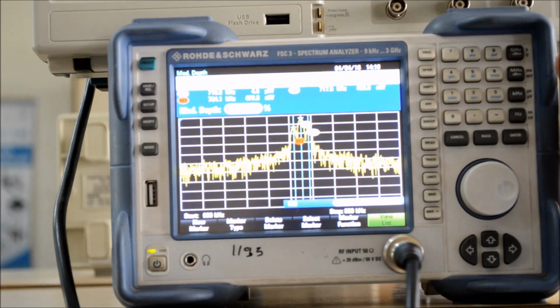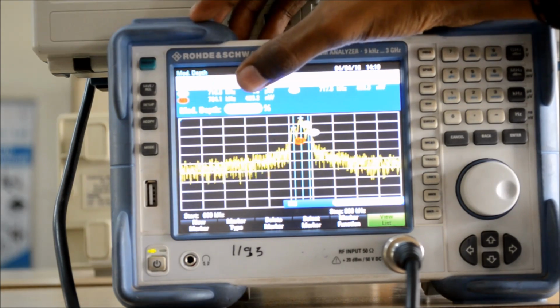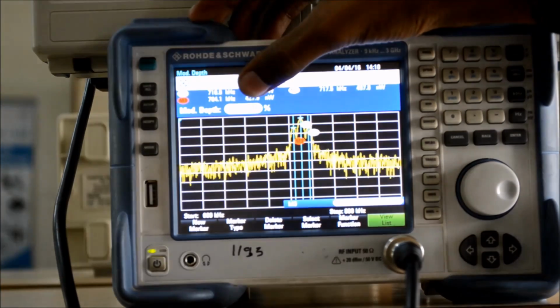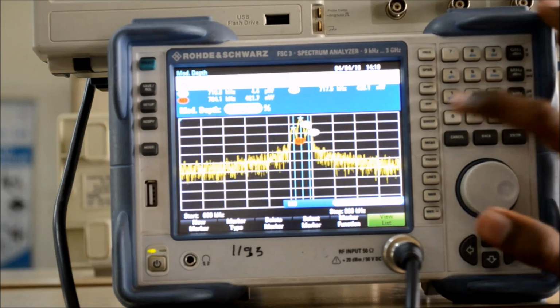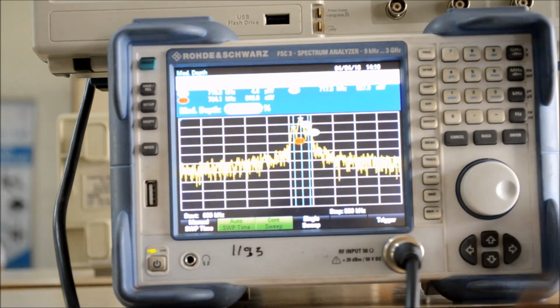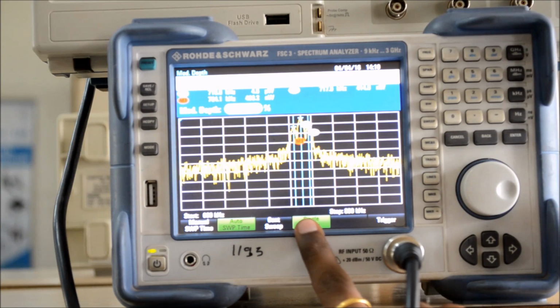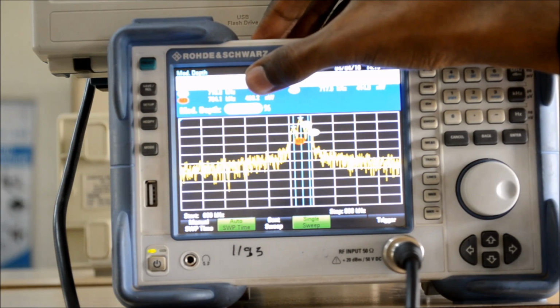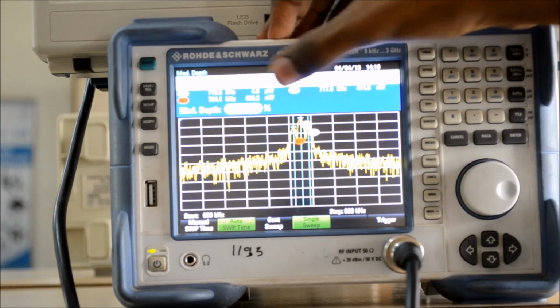So with this, you are able to find all the positions and the amplitude modulation, which is at the moment around 60 to 70%. To get the final output, press the button sweep and press single sweep. By single sweep, it will just pause momentarily, and you can find the modulation depth, which in this case is 63.66%, and the values at the markers.